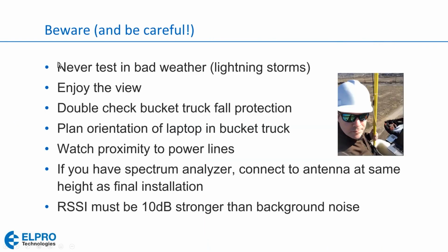Okay, so a couple of things to be careful about. Never test in bad weather. Lightning storms and radio surveys do not go well together. While you're up in the bucket truck, be sure to enjoy the view, because it's a rare treat to be able to survey the land and really enjoy the view. Double check your fall protection. Make sure you've got your harness on and it's properly secured. These bucket trucks can be quite dangerous, and they can move rather abruptly.